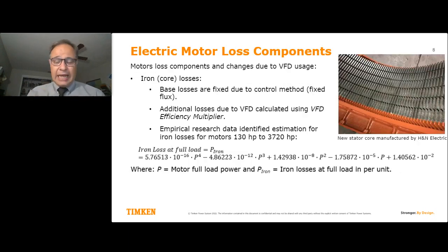So I had to take the electric motor and calculate the known losses. These are very well defined by NEMA, IEC and IEEE, and there have been many papers written on what these losses are. However, adjustment for variable frequency and variable speed became very, very difficult to find. So as a start, I had to look at the iron losses, which are because of the flux.